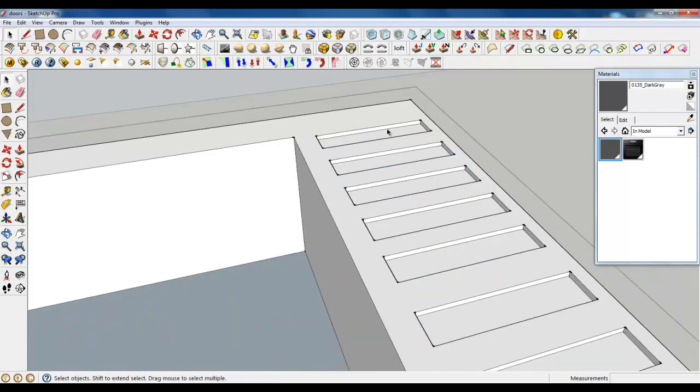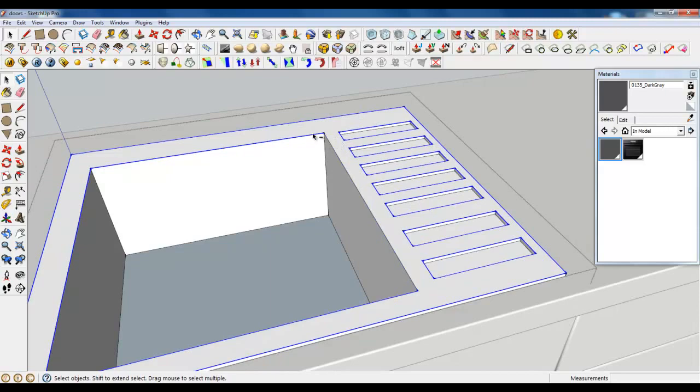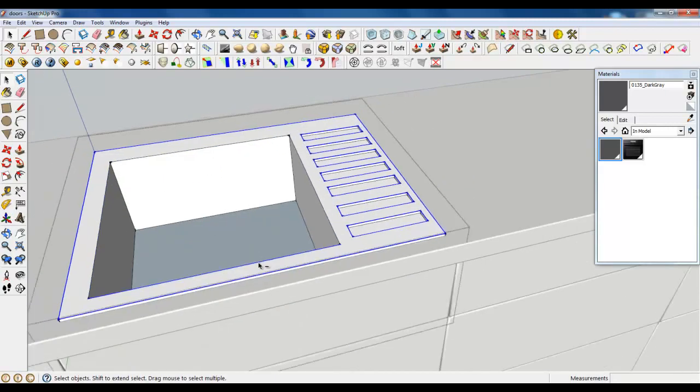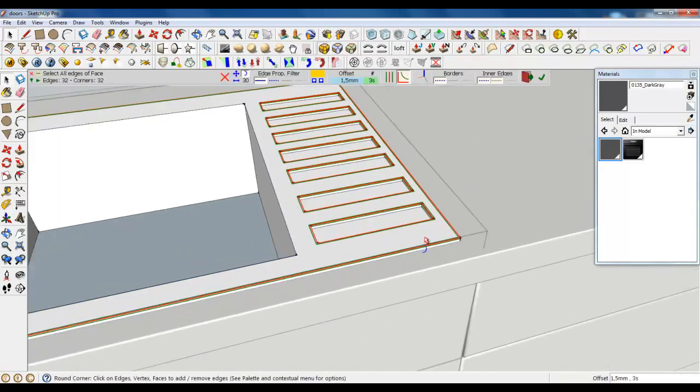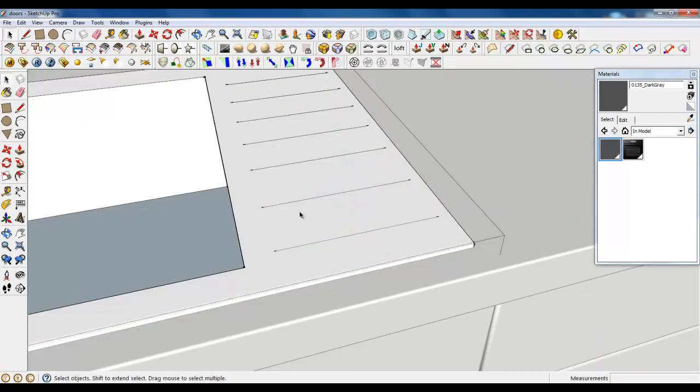It's very good now. Okay, so 2 clicks to select all the edges and plane, deselect plane, and also these edges. Now we're gonna round. Well, 1.5 millimeter and 3 segments is perfect, so let's click calculate. It's processing pretty fast, and also delete unnecessary planes.